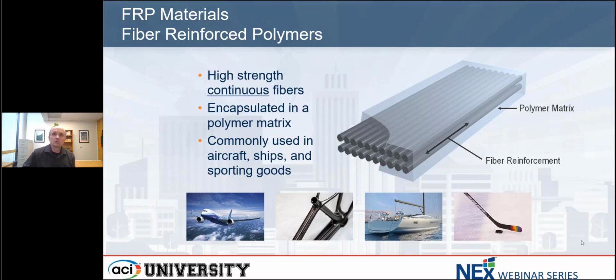These materials are all using, though, continuous fibers. So I make a point of this because the fiber material that's reinforcing these materials are all continuous throughout the entire length. This is not to be confused with fiber reinforced concrete, where you might have discrete chopped fibers that are kind of distributed in a concrete mix. This is a completely different animal. This is continuous fibers that are reinforcing this material along its entire length. And it really gives this material very high-end structural properties.